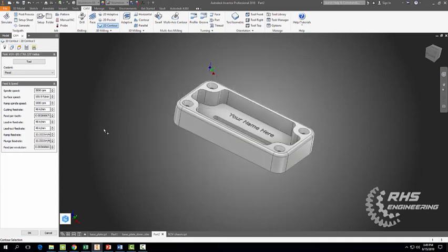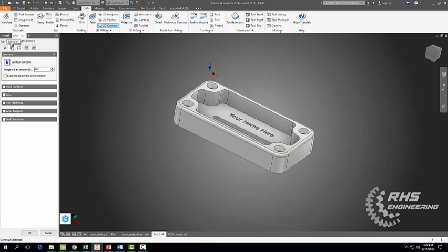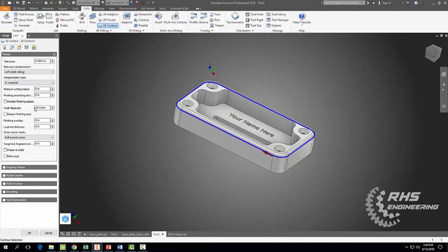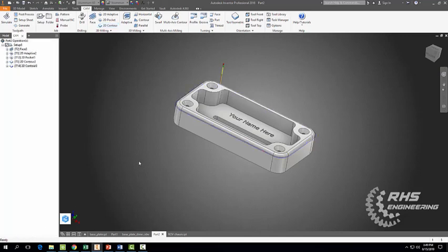So let's hit select. Okay, once again, let's change it down to 3000 and give us a feed rate of 20. All right, under passes, or excuse me, under geometry, we're going to select right here. Okay, and under passes, same thing as last time. Finish feed rate says 20. Leave these unchecked and hit OK. Okay, and you should hopefully end up with the following toolpath.